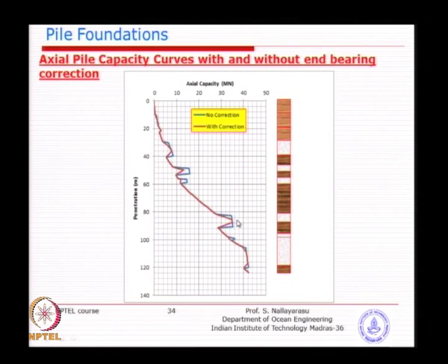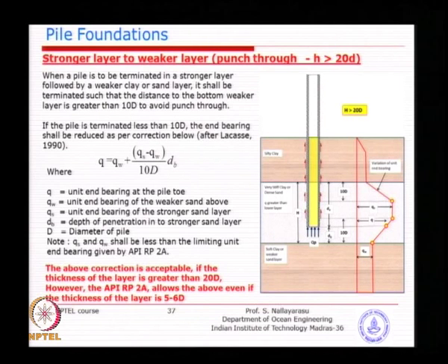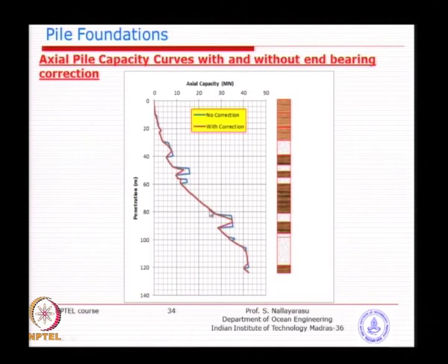We have a sand layer preceded by clay or less dense sand, and also followed by either a clay or a sand which is less strong than the layer in question. So, what we need to do is apply and compile both, one forward and the other backward. So, both reductions have to be done, and that is what you see from this picture. If you go back here, we have done a forward reduction, we have done a backward reduction. You come from the bottom and join.